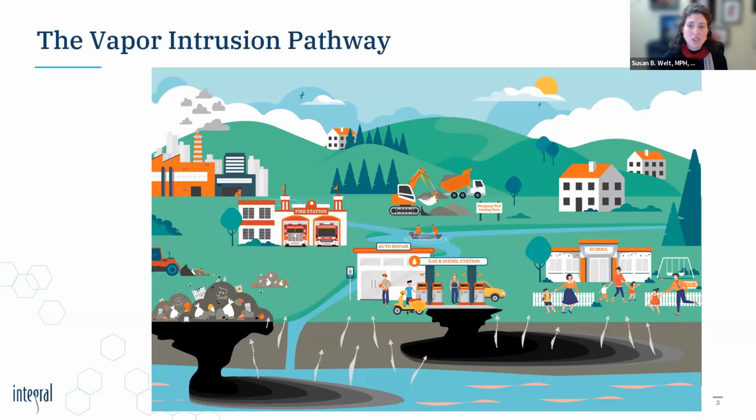If one or more of these conditions is currently absent and is reasonably expected to be absent in the future, for example, vapor migration is significantly and persistently impeded by natural geologic, hydrologic, or biochemical processes and conditions, then the vapor intrusion pathway is referred to as incomplete. Although it may be currently incomplete, the pathway may exist and therefore it may also be considered a potential pathway to be addressed in the future when conditions change. We all know that environmental conditions change, and so therefore we have to think about whether or not that potential pathway will remain incomplete.